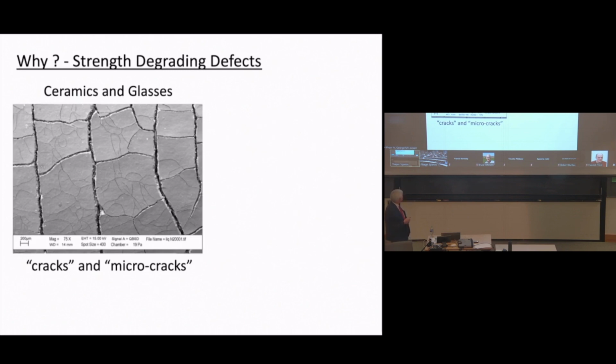And what limits the strength of this material is basically, as you start to stress it, one of those cracks is bigger than the rest, and that crack then propagates, and when it propagates, it just cuts through the material and busts it into two, and you end up with a mess, right? And so the point is, it's the defects in the material that are important.